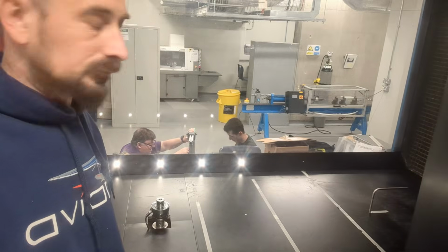Now, in our case, of course, we're quite lucky because we're actually testing the actual components in there, which means that by definition they're one-to-one scale, and we're running the wind tunnel at the kind of speeds that a hang glider actually flies at, and so it's fast enough to be representative, and the parts are the actual parts, so there's no need to apply any scaling factors in this case.